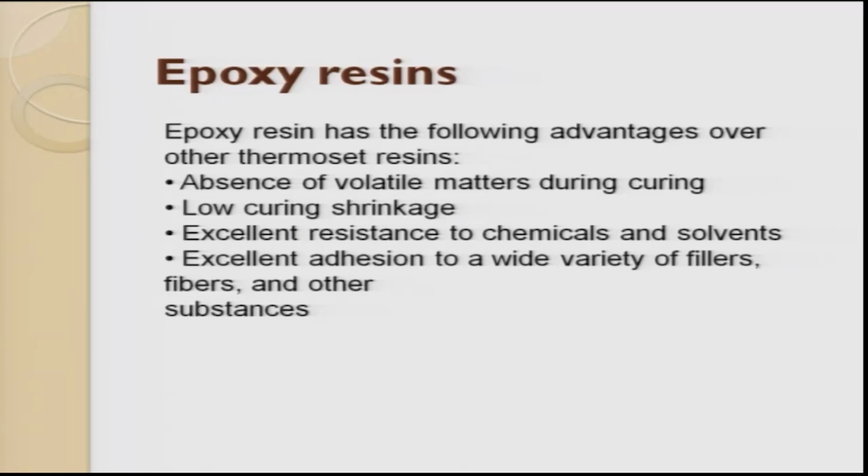See, it is a very important property. If you don't have a good wettability property, then matrix and resin will not get locked and you will really not be able to enjoy the advantage of a composite material. The enjoyment of the composite material comes if you have a proper link or proper bonding between the polymer and the reinforcing agent. Epoxy gives that in a big way. So that is why epoxy resins are exhaustively used under thermoset category for various polymer matrix manufacturing.